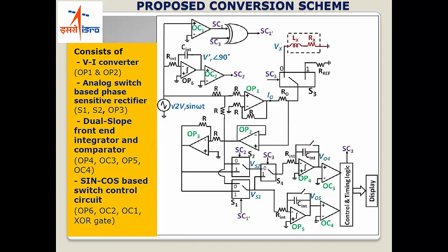Okay. So the objective is to measure both L and R in a digital format without using any conventional ADCs. There's nothing wrong in using an ADC, but it's an additional element, a VLSI element sitting inside your circuit. So what if you could have all of it in the analog domain itself? You could have a faster measurement technique possible.